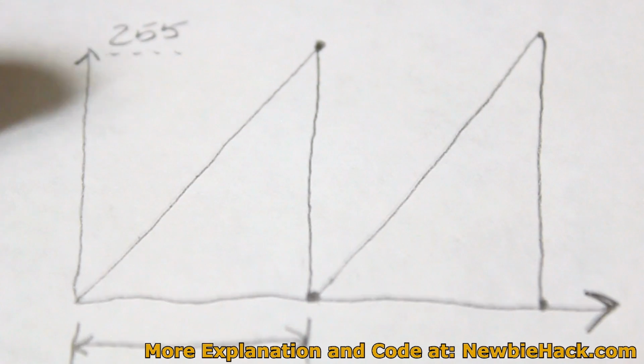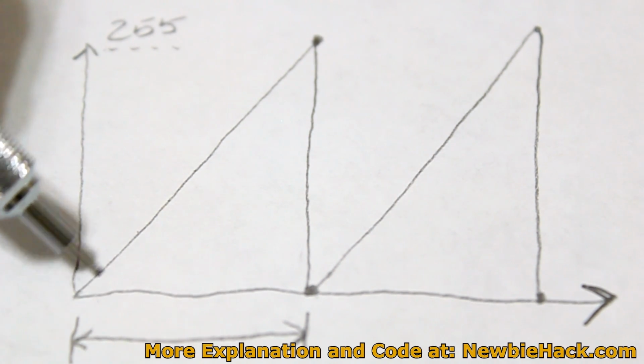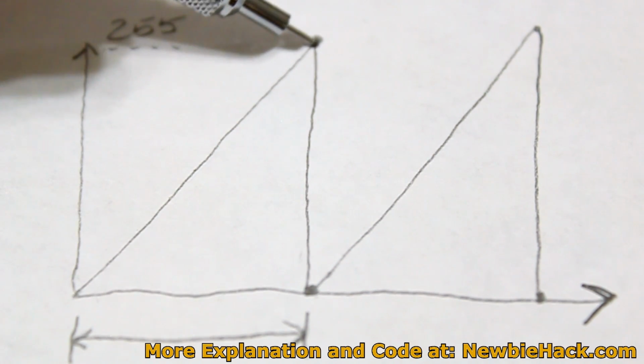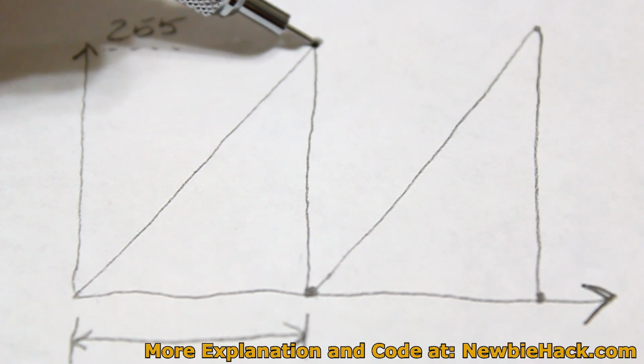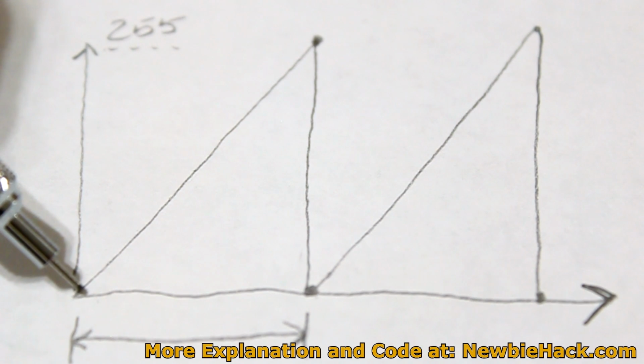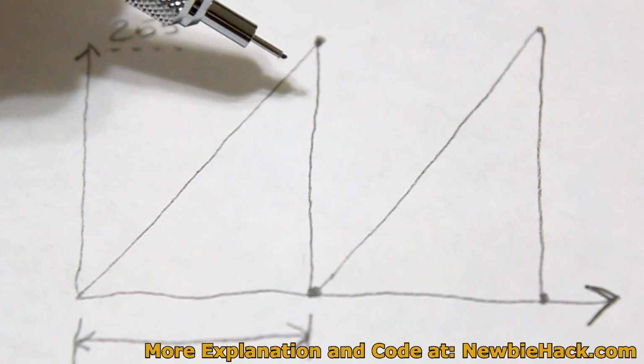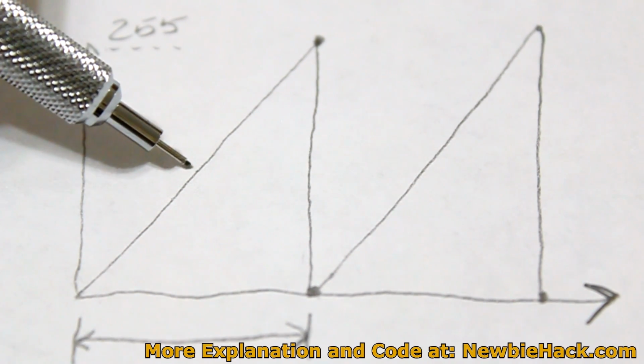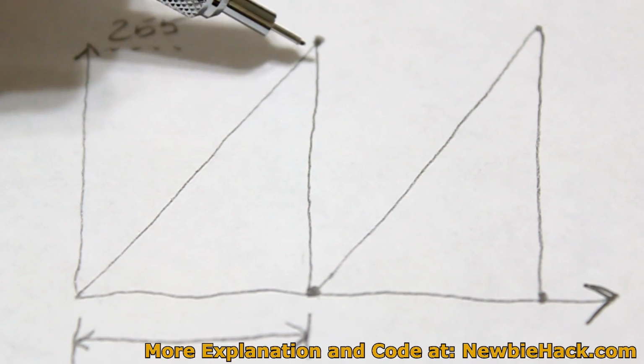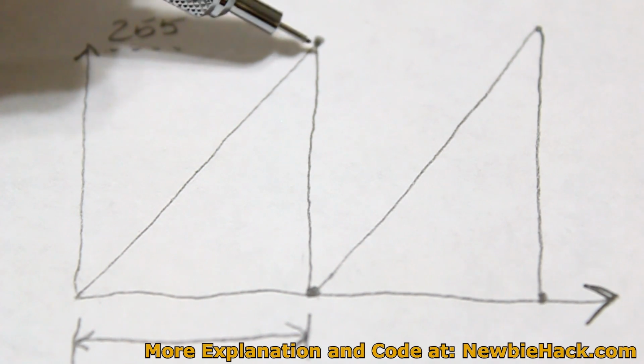If we have no prescaler, this is counting with the internal clock in the microcontroller. Right now, by default, the microcontroller has a 1 megahertz clock, or it is counting from 0 to 1 million within 1 second. Hertz means per second. Whenever you have a megahertz, that's 1 million, and hertz means 1 second, so it counts 1 million times within 1 second.